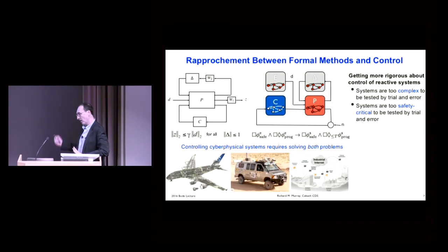So I do a lot of work in aerospace controls. The spec for aerospace controls is this: all controls work is software these days, and any software package running on an airplane in a safety critical function, like the flight control computers, you have to demonstrate as engineers that you'll have no more than one failure every 10 to the 9th flight hours.